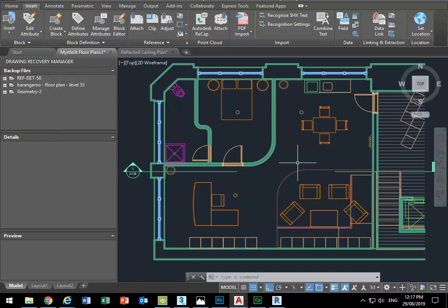So once you understand that basic principle, it's meant to wake you up when you're sleeping, and so you need to have it separating or between any sleeping areas and the rest of your unit. So in this case, where do you think it would go? Exactly, right in front of the bedroom. Yep, right next to the bedroom door. Now, if you've got a hallway, say you've got a hallway serving a bunch of bedrooms, then it needs to go at the end of the hallway, in between the bedrooms and the rest of the living space.